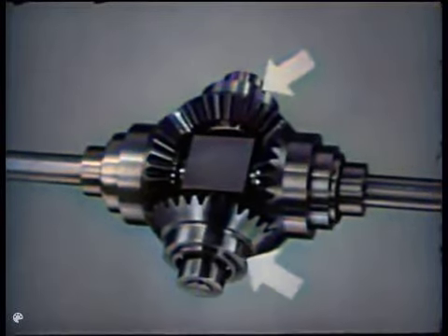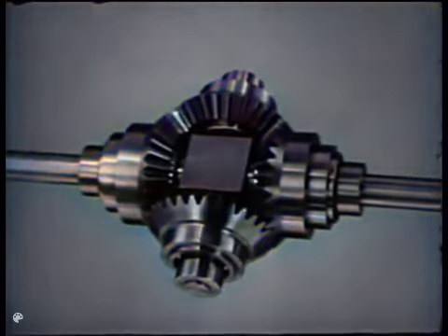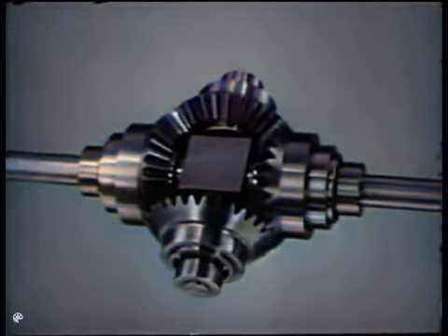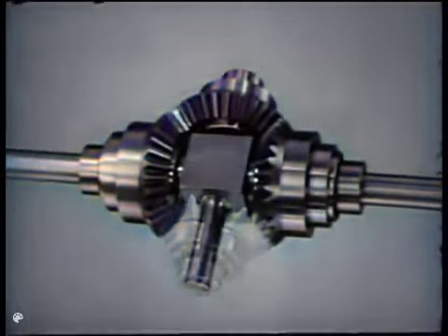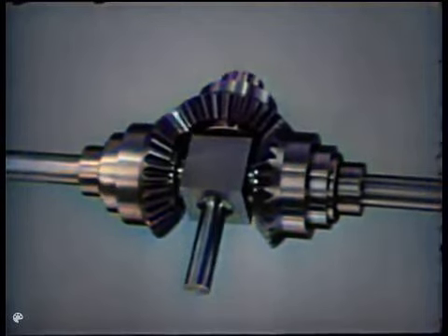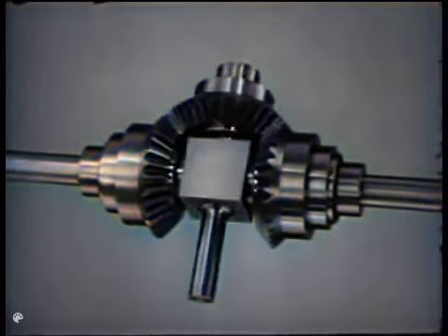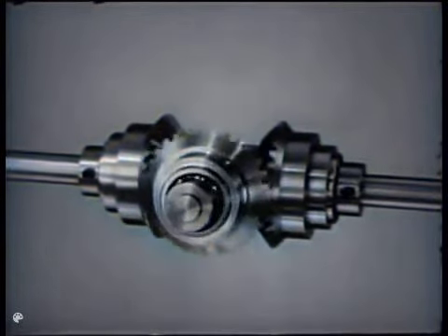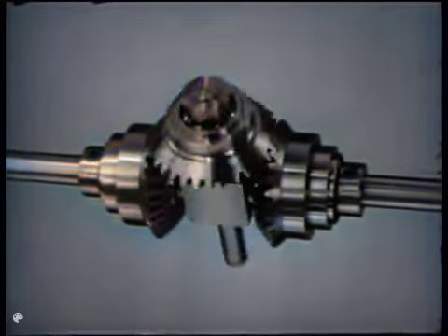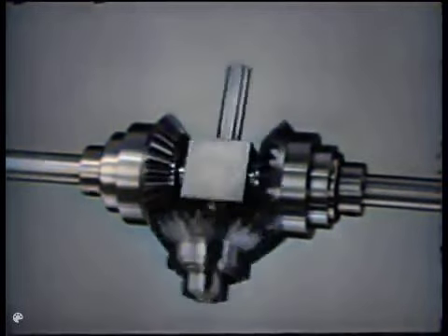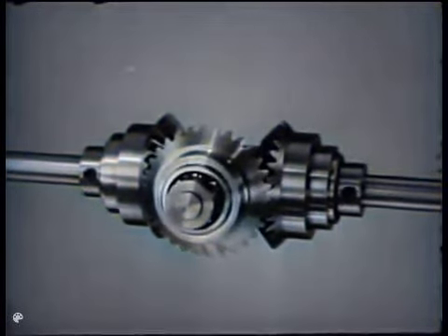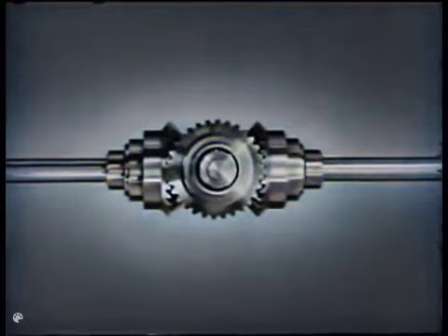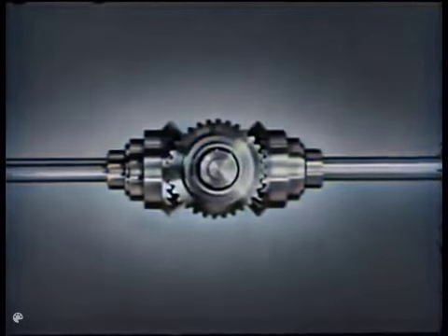Although there are two spider gears, only one is needed for the mathematical problem. The other is there to balance the mechanism. So we can remove one spider gear, and we now have the basic elements of a differential. To study its operation, it is necessary to count and compare revolutions of the end gears and the spider shaft. That isn't easy to do. We'll show the differential action in a way that's easier to follow.